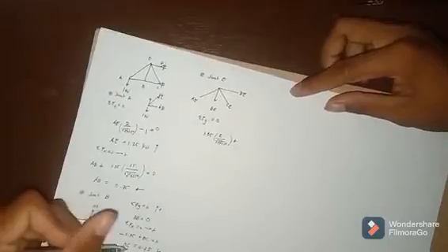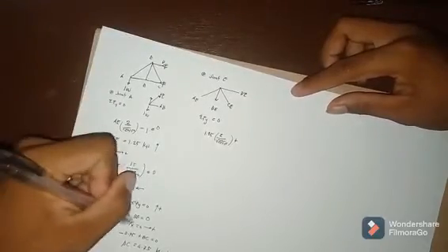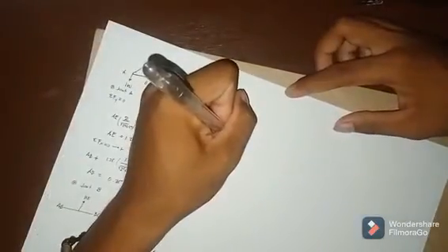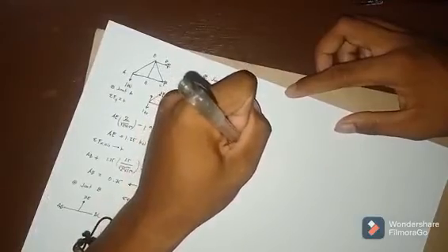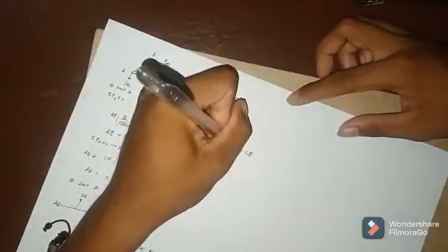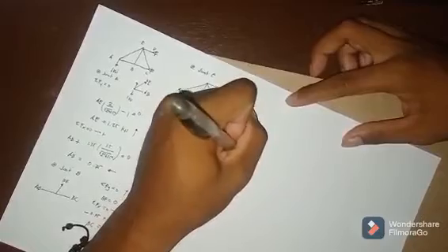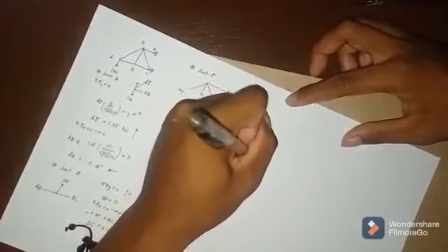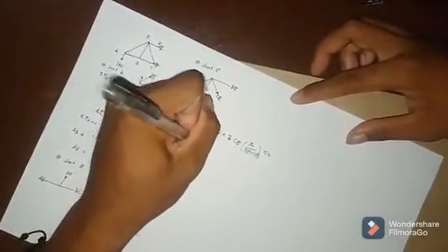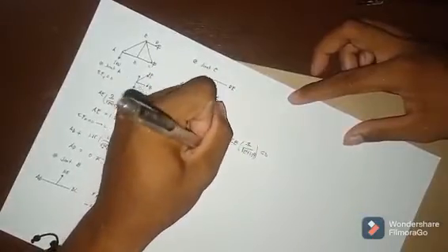the BE, which we can see from our previous solving is equal to 0, and our CE vertical. Plus CE, we consider tension, so we can say that this is negative because it is facing downward, so negative CE times the vertical, which is 2 over square root of 2 squared plus 1.5 squared, equals 0. So CE is 1.25 kilonewton and facing downward.